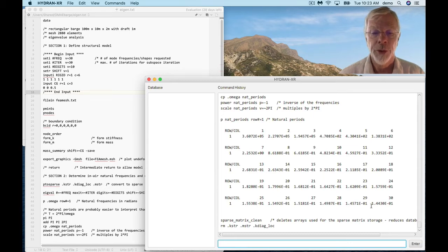We know that there's very little wave energy below around 5 seconds. So these periods are well below where the significant wave energy is. And so that's a good thing because that means we're not going to get resonance. That doesn't mean to say that the larger wave periods don't excite these smaller natural periods of the structure. They will, but we won't be having resonance.